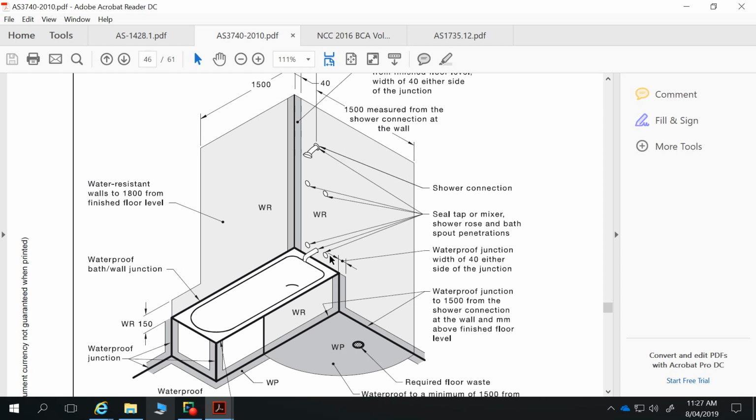So waterproofing at penetrations can happen via either the painting of waterproof membrane in around your tap body and then siliconing in there, or there are actually proprietary waterproofing little seals that can be pushed in there. So if you cut the holes neatly with a hole saw when you do your penetrations, you can push these rubbery cups in there that produce that waterproofing.